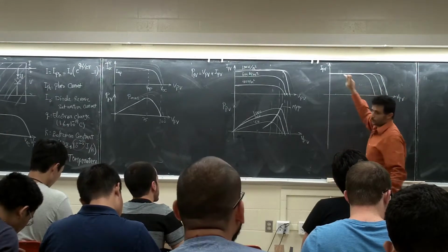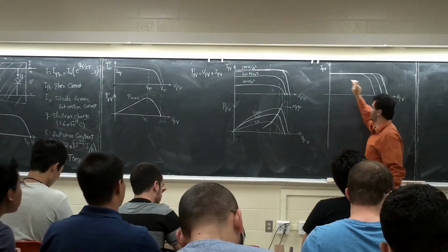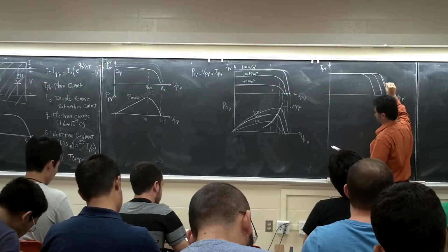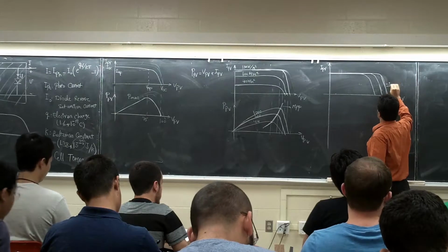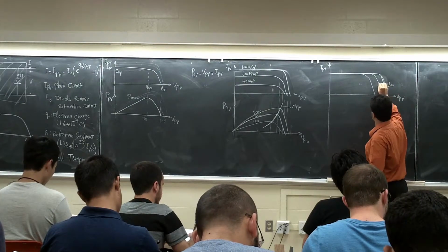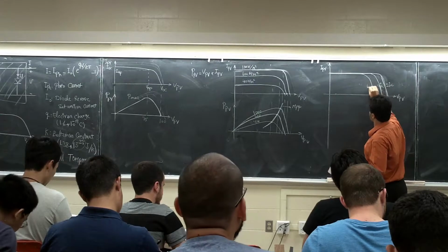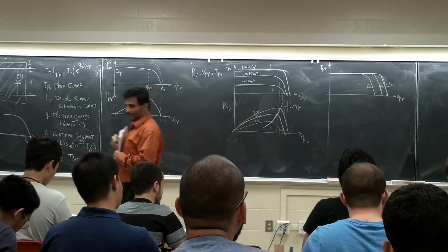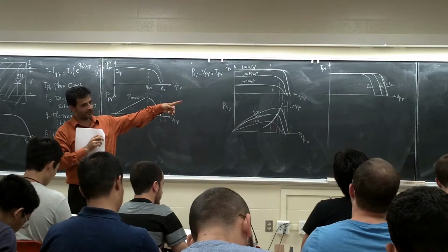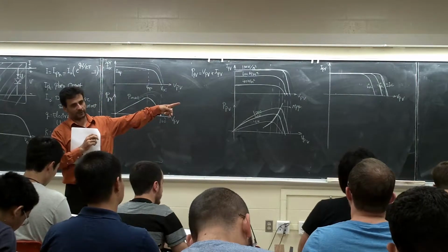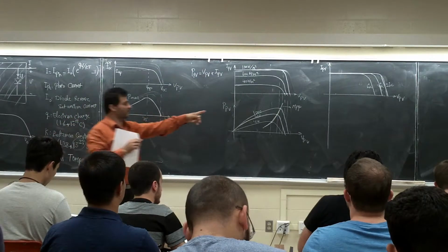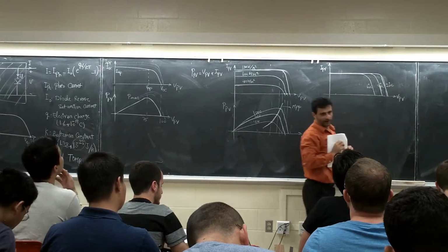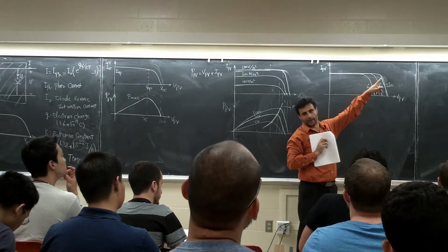This one is going to have no change here, then temperature is changing, but V open circuit is opposite of this one. For example, this is 20 degree C, this is 40 degree C, and this is 60 degree C. Which one is better? Definitely the 20 degree C is going to give you better power. Why? See, for all of them, the current is almost the same, right?